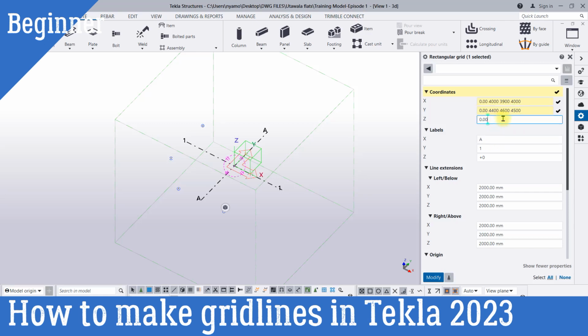Next is the Z axis. The Z axis will depend on the number of levels you want to model for your design. We are doing a simple design with a lower ground that is voluminous because of the movement of machinery and the goods in and out of the warehouse. I'll assume a height of 4500, that is 4.5 meters, and then the upper floor will be 3 meters, that is 3000. But for the height, I'm going to use cumulative height here so that I can get the total height as 7500.